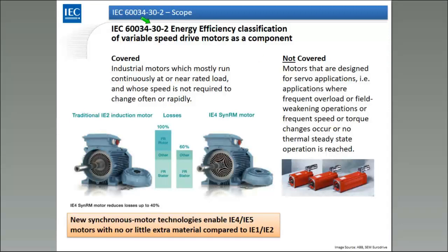Again, 30-2 is not for servo motors, not for servo applications where we have frequent overloading, field weakening operations, speed torque changes, no thermal steady state, and so on and so forth. These motors are really, really different.